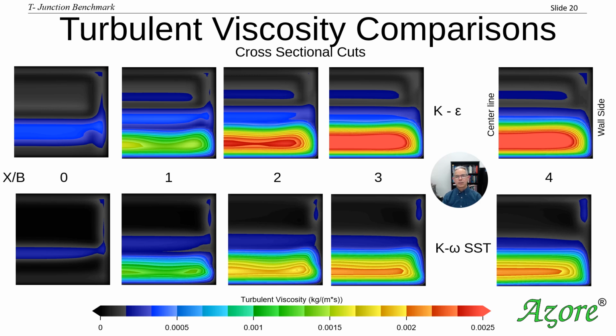So now we've looked at the experimental data, so we see that turbulence is important there just by visually looking at the flow structures. And we've looked at the comparisons, our CFD predictions, and how well it compares to the experimental data. But before we finish this discussion, I thought it would be good to look at the turbulent viscosity specifically and what its flow structure, this scalar value, looks like as we go down the duct.